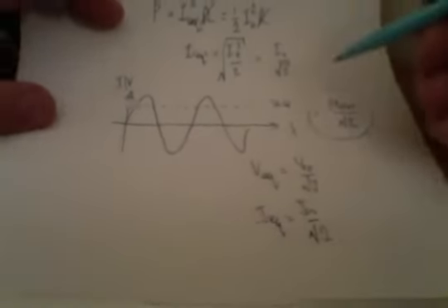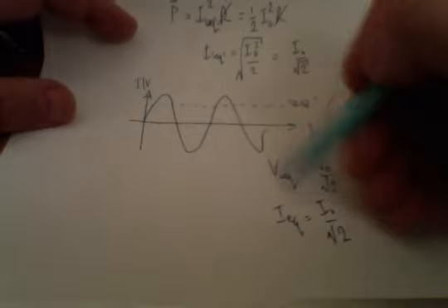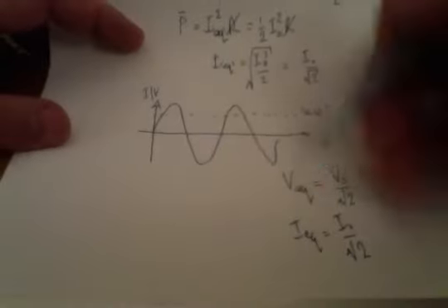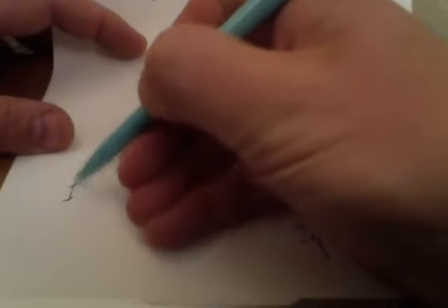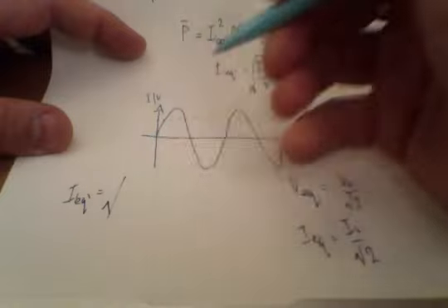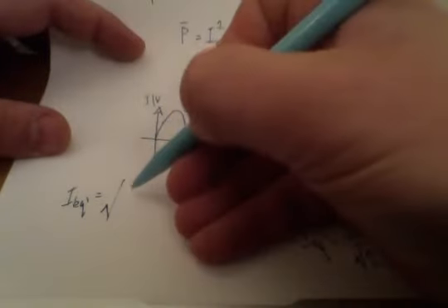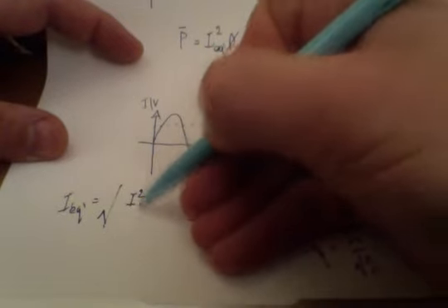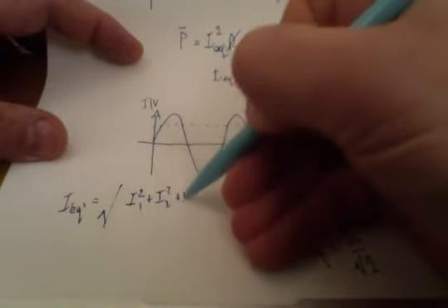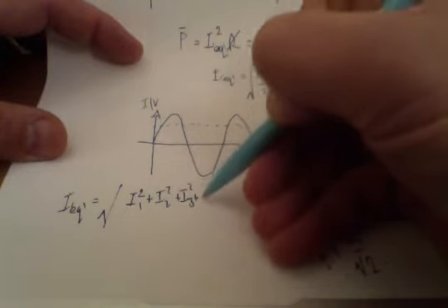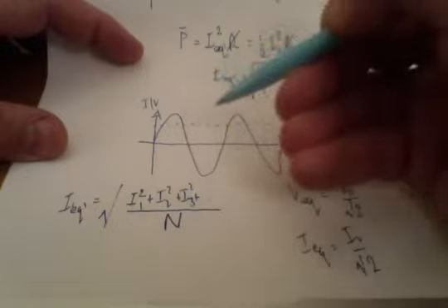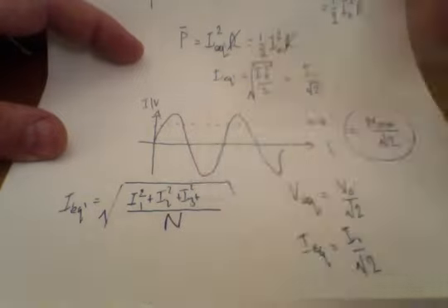Now, it's important here that we cover one area. Writing equivalent is not actually correct, because what we have actually done is I equivalent was actually the square root of all the I squared values added together, divided by however many there were, and then I square rooted it.